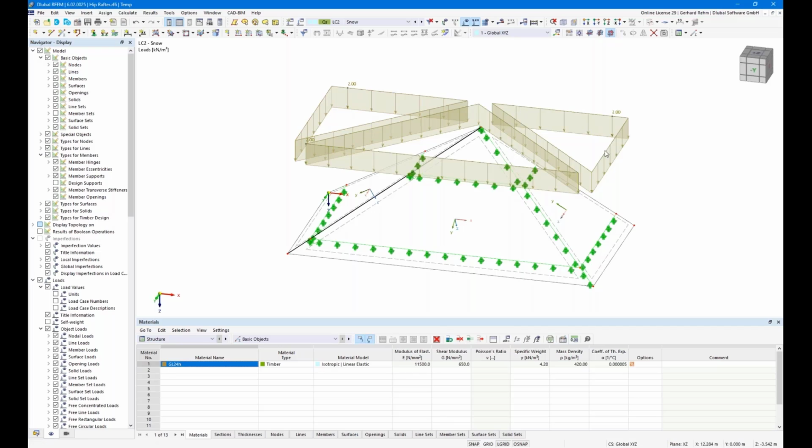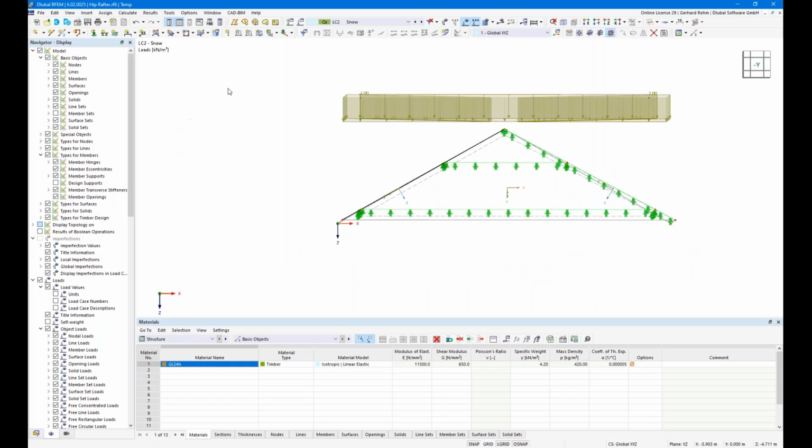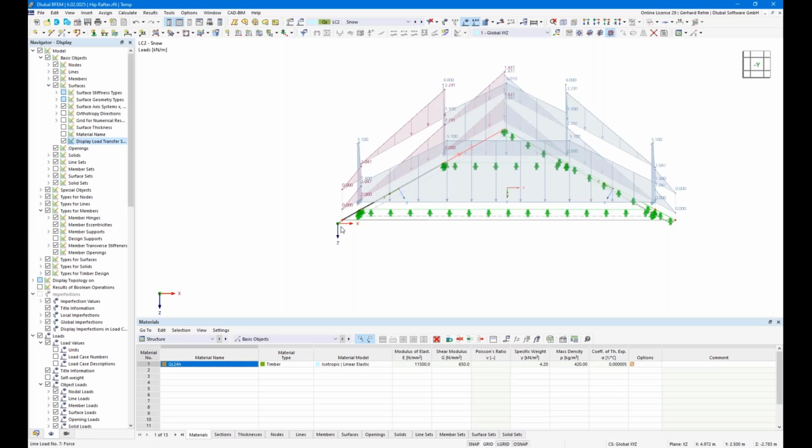You see the loads are applied in the projected area, but the internal process converts them automatically to the true length. You must imagine it's a kind of umbrella. When you flip the umbrella, it gathers all raindrops. It does not matter in which direction, whether it is gravity direction, or a mix of gravity and lateral direction. So the loads are always displayed in true length direction. But it's converted correctly, of course.